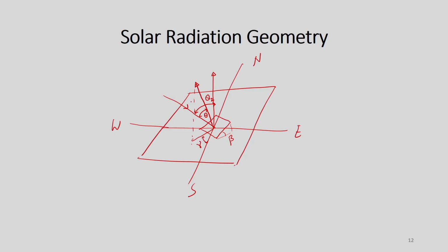And if we project this one here on this plane, the kind of angle we will get is the solar azimuth angle, and this is alpha a, your altitude or inclination angle. This is the sun, because the sun is radiating this beam energy and it is falling on this inclined surface.